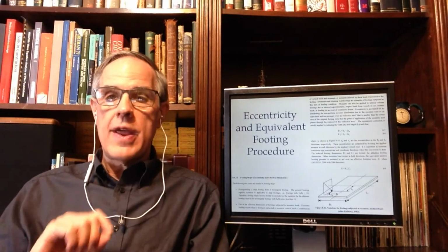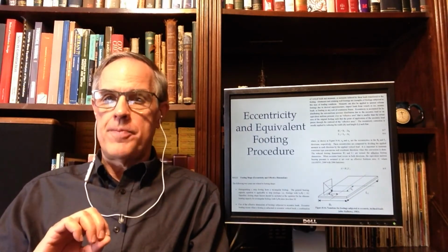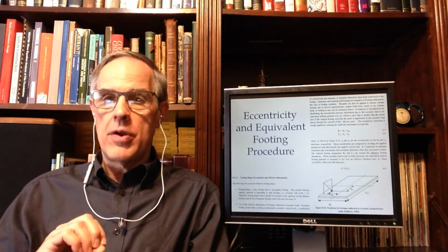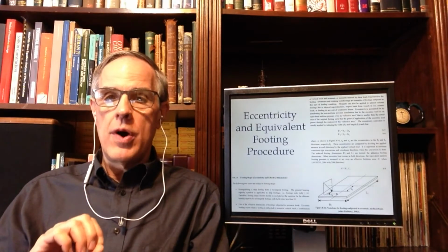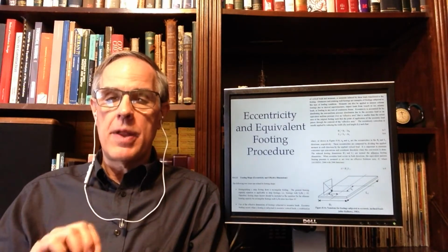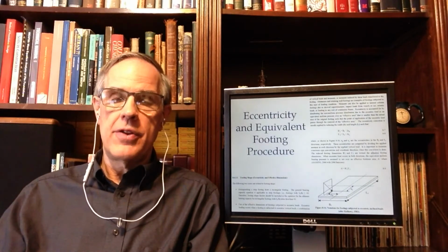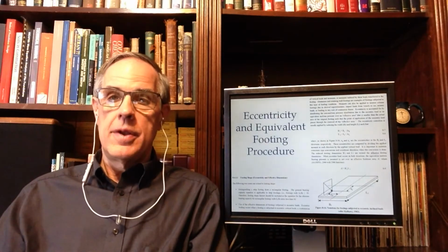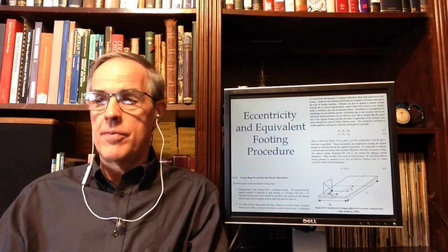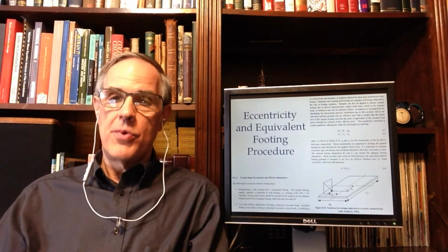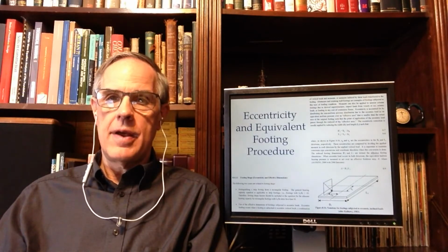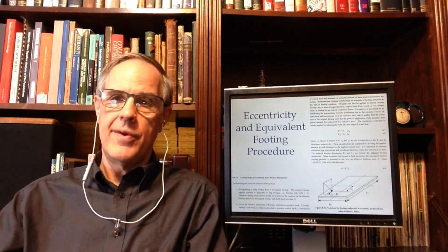Once we do that, we have a reduced foundation, a foundation which is smaller than the original one, but one where we can actually apply our theory to determine whether the foundation will withstand the loads, whether it will meet bearing capacity and or settlement configurations. This is an important concept that over the years my students have struggled with.